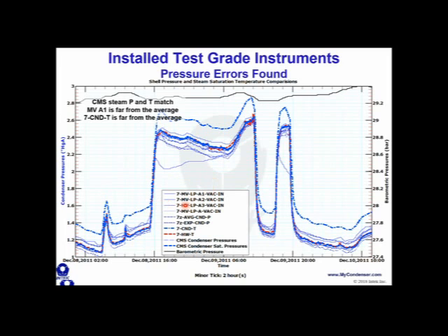And so I'm going to point out these values on this graph because I know this plot's very busy. These are 3 independent measurements, all measuring the pressure on the same condenser, same space. Should all be at the same pressure. And so you see these 3 very good vacuum gauges at this pressure, and that pressure. Almost 3/10 of an inch spread at this particular point. That is way too much. Your condenser pressure does not vary more than a few hundredths of an inch across the shell.